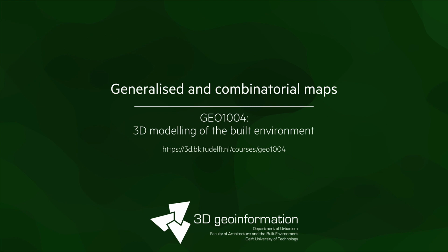The topic of this lesson is two related data structures, generalized maps and combinatorial maps. These are rather special because they can be used to represent data of any dimension, including in 2D and in 3D. In 2D, combinatorial maps are equivalent to most half-edge data structures, which means that we can use them to store sets of polygons and the topological relationships between them. But the advantage is that by simply moving to 3D combinatorial maps, we can also store sets of polyhedra, including the topological relationships between them.